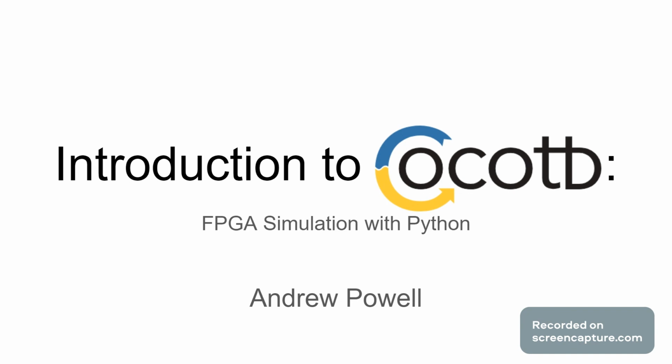So without further ado, allow me to introduce cocotb, FPGA simulation with Python. For those who are actually watching, if you only learned one thing, the one thing to get from this presentation is you can do Python-based simulations for digital circuit designs using cocotb, and the big advantage there is you get to do your simulations while having all the access to the Python libraries and tools, which is incredibly helpful.